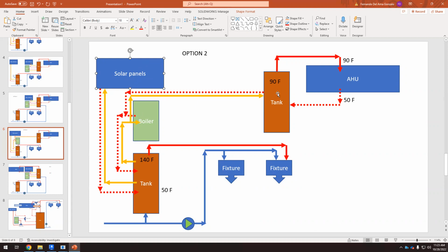We don't have this nasty weather. So we can save energy in residential buildings with solar panels, but only for the domestic hot water. We don't connect solar panels to the heating system. We have a boiler, and then the boiler is shared with this tank and that tank.